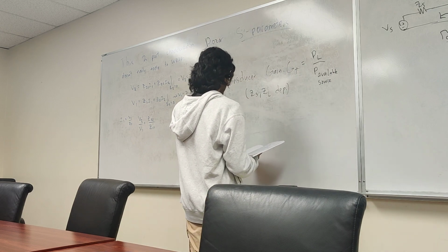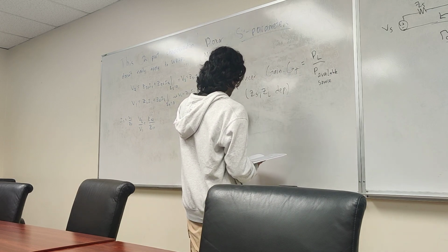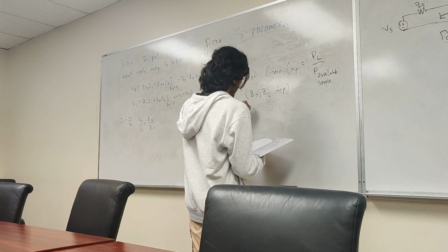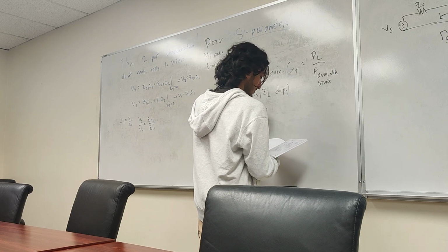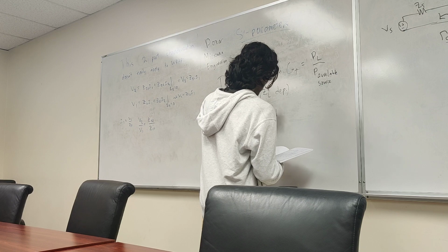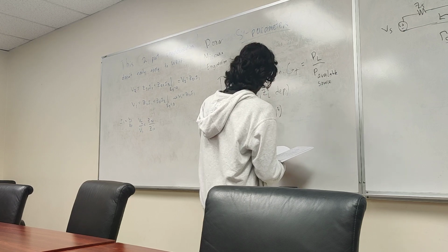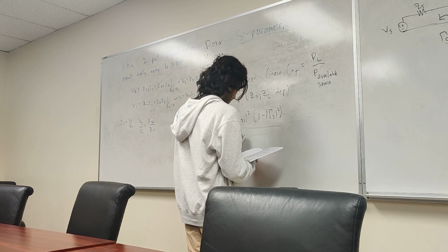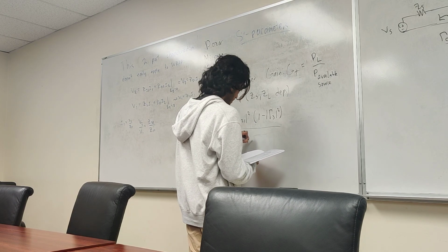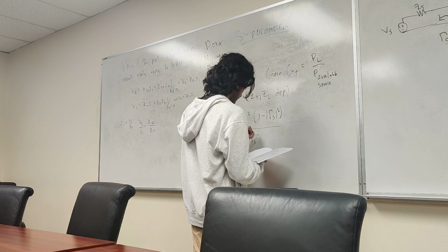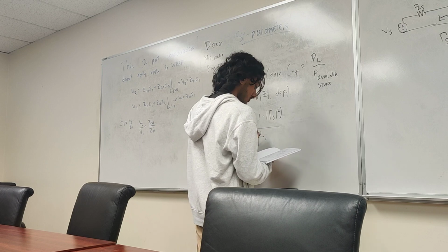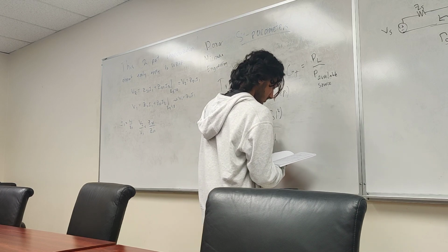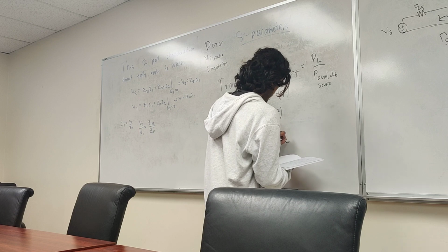We have an equation for this gain. It's going to be quite a lot. It's the magnitude of S21 squared, times 1 minus the magnitude of the source reflection coefficient squared, over 1 minus S11 times the source reflection coefficient, all that magnitude squared, times this.